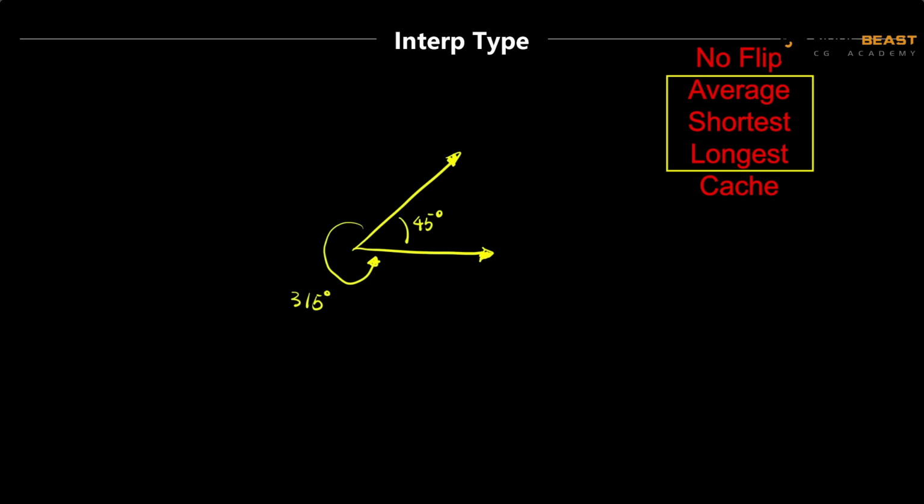Now, in the 3D world, this is actually a bit more complicated. Because we have three axes, Maya doesn't just simply average the angle for each axis. If we look at the Maya help documents, we'll see it's actually based on a quaternion averaging algorithm. But anyway, from a practical standpoint, because it's just a simple averaging algorithm, and our rotation we know we're using three XYZ axes, it can run into gimbal lock situations under certain conditions.